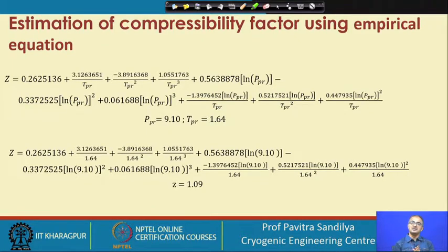So these kinds of things are very much expected in the natural gas literature because of the variations in the natural gas compositions. Here we just see how we can estimate the values of this compressibility factor using some chart and using some correlations. And when you are going for field work, there you have to figure out what is the appropriate correlation that can be used for the particular case.